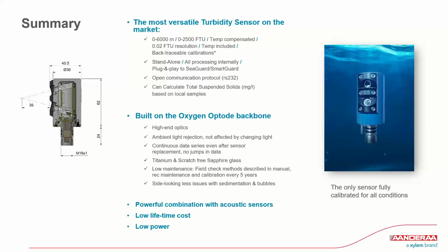And we see from previous experiences, for example, with sensors which are molded at high pressure, the electronics can drift over time. Sapphire glass is also a good thing, because it's very difficult to scratch, and if you scratch a window on a sensor, that can also appear as a drift, and then you must do something to fix that sensor.